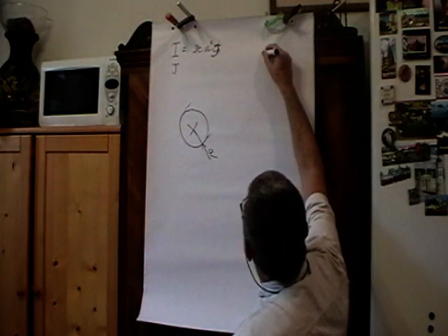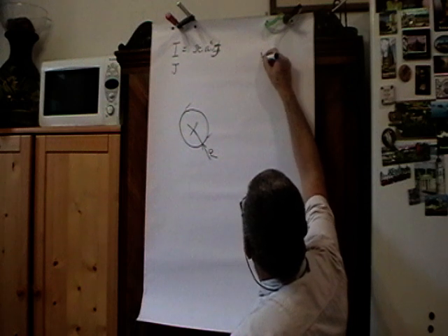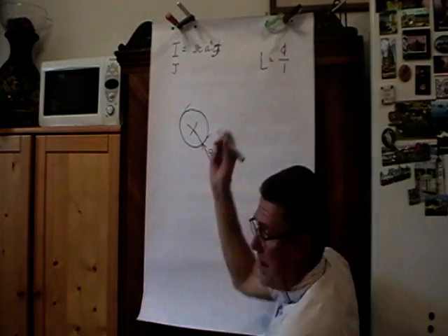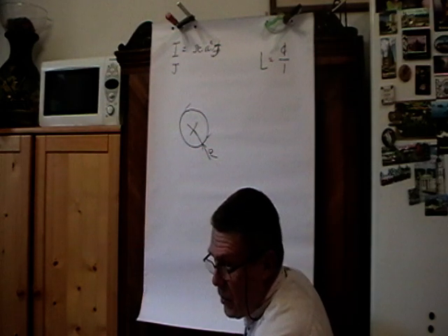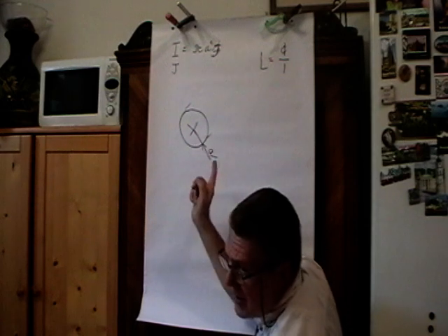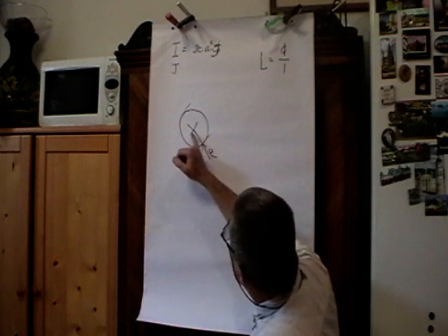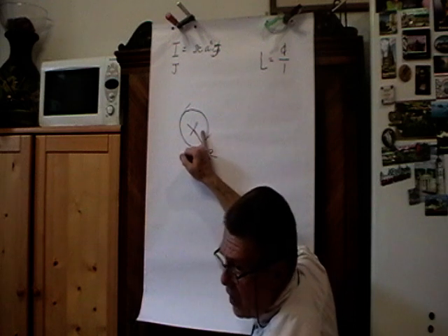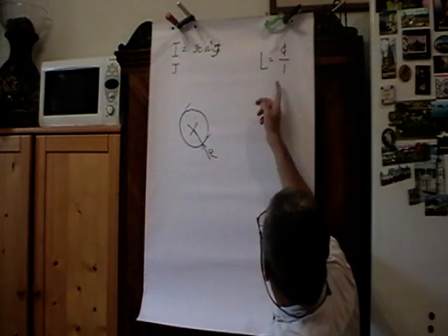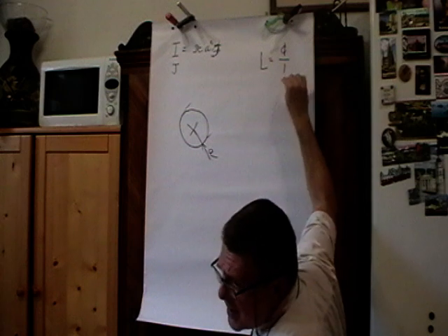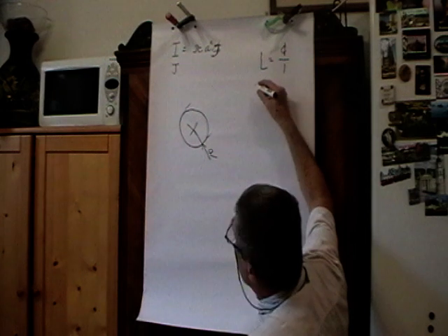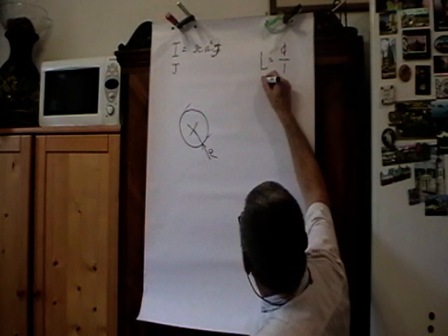If you have the definition telling that the inductance is the ratio between flux and current, well, we might be able to calculate the total flux that flows in the core, but the problem is that each part of the flux is caused by a different current. Remember, this equation says you divide the flux by the current that caused it. But remember Ampere's law.